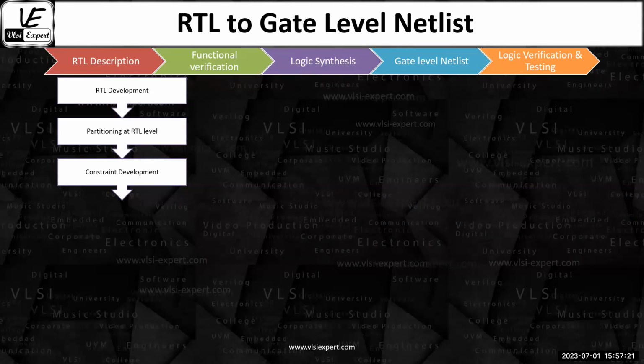Now you have divided that 4 seconds into nanoseconds. This particular portion is supposed to do the addition in 10 nanoseconds. So now you need an RTL. RTL is what? Later on you are going to convert it into the circuit. That RTL should give you the result in 10 nanoseconds.